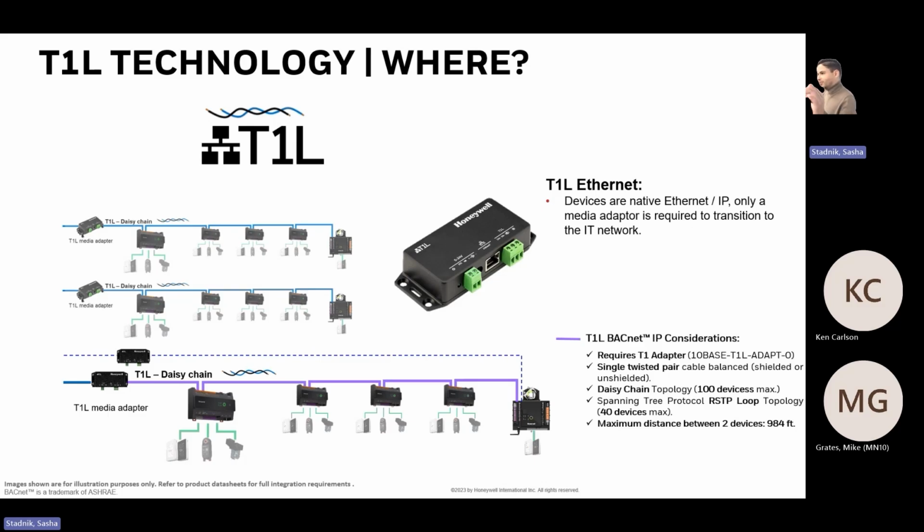I really apologize if you already talked about this, but the dotted line going back to the controller, what was that? That can be a loop. You can actually have a second fail-switch mode through T1L. The first one is between the controllers. If this one fails communication, the switch here closes, this controller disappears and becomes like a line, and communication flows from this controller to this controller. But if all of a sudden you start to lose this one too, what is going to happen? It's going to close, and here's the problem.